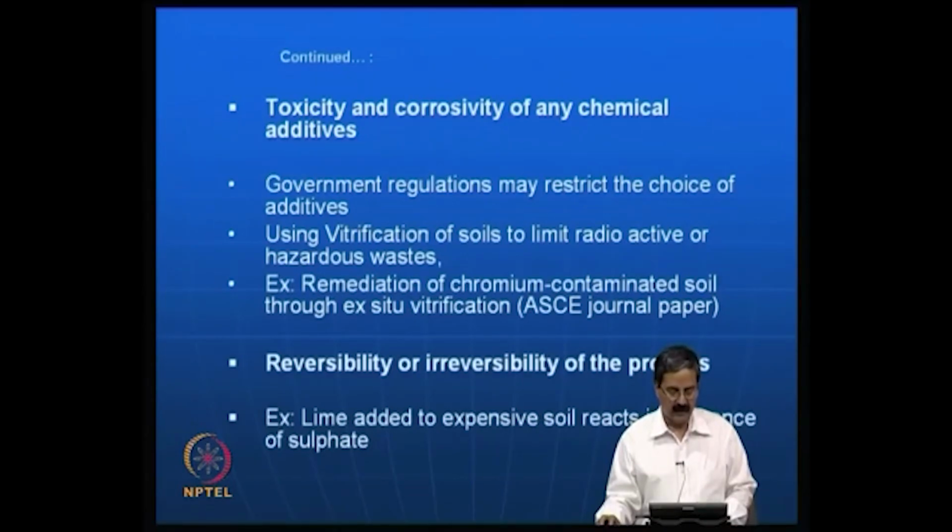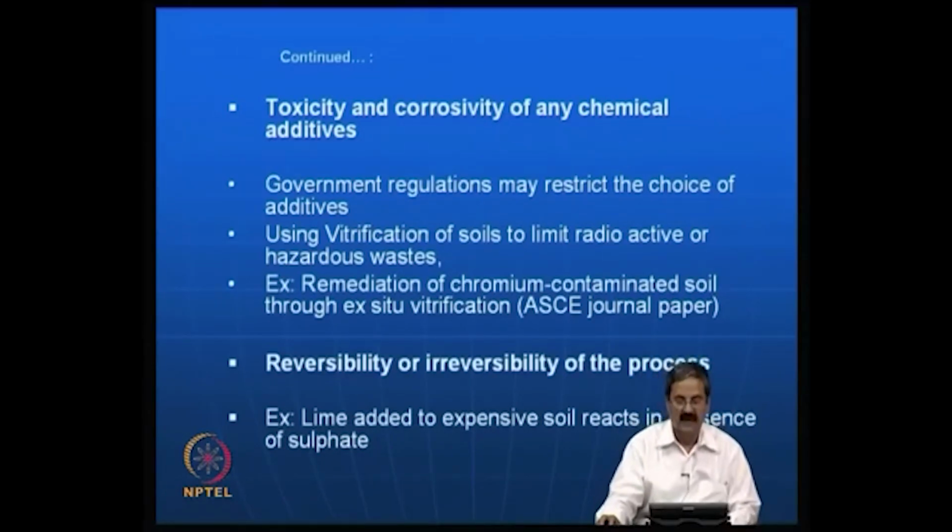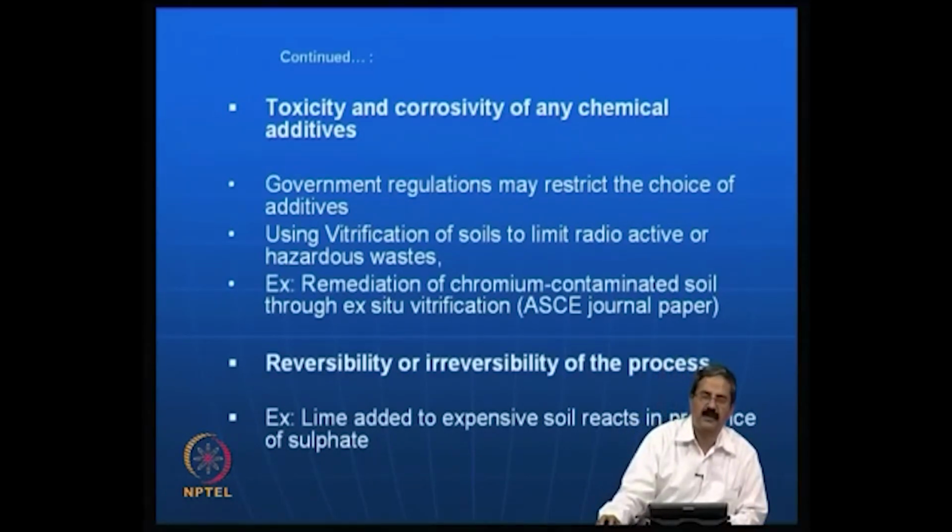Another important point that governs the choice of ground improvement technique is the reversibility or irreversibility of the process. Actually, people have been using lime for expansive soil treatment. What we hope here is that the soil will not swell when you add lime, that is our assumption.